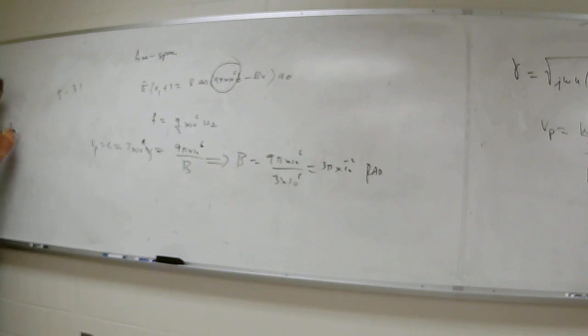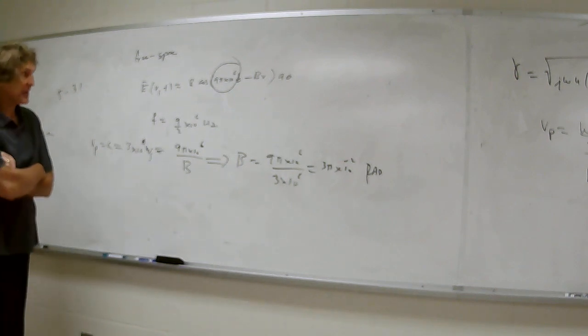Sigma would be 0. It'd be square root of mu over epsilon. It's eta naught, or it's 120 pi ohms, right? 377 ohms. That's nice because in your circuits problems, they always use 60 hertz, and you get 377 there too for a constant, 2 pi times f, right? So that's about 120 pi ohms.